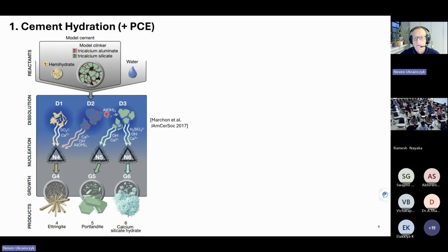Aluminate ions, they are all dissolving from the minerals. So it's dissolution of minerals, and we have them in the pore solution, it's called, because it's inside the pores. And then when they become saturated, or actually we need to oversaturate because we have these nucleation barriers to form the first nucleus. And when we form the first nuclei, then we start to precipitate.